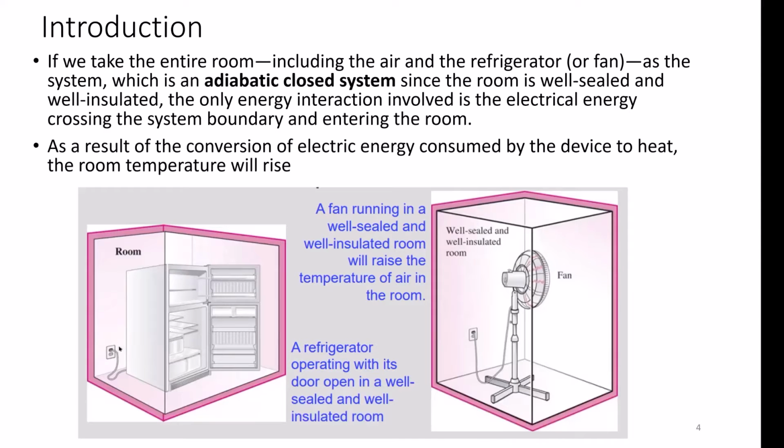And the only energy that's coming in is electrical energy. Okay, so what's going to happen is that, in both cases, you have electrical energy converted to mechanical energy in this case, and it circulates around the room. And you have a conversion factor, like the motor, and there's friction heating up the air when the fan is spinning. And so you have some conversions where you're actually generating heat. So in this case, you'll heat up the room.